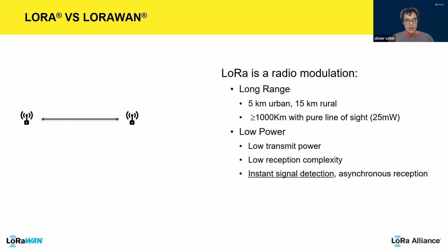Typically, the efficiency of a radio power amplifier is around 50%, meaning that 50% of what you want to transmit is transmitted as radio waves, and the same amount is dissipated as heat in the power amplifier, and this is the dominant part of the power consumption. If you don't have a constant envelope modulation, the power efficiency goes down, maybe sometimes to 10%. So 50% is a good number.